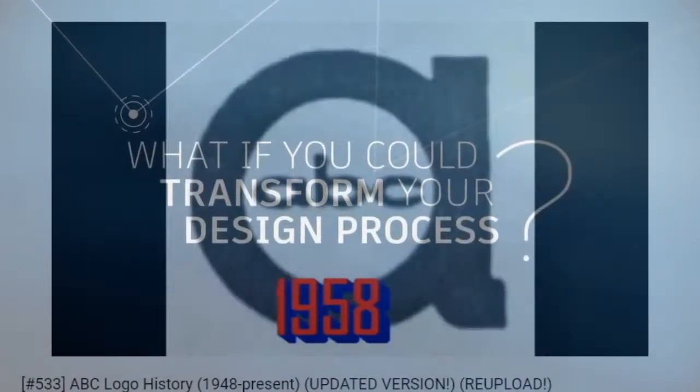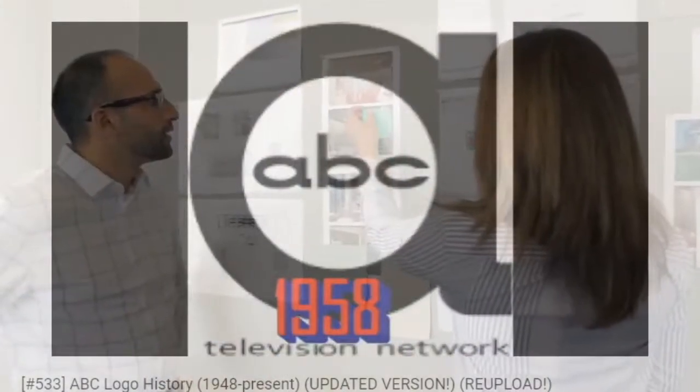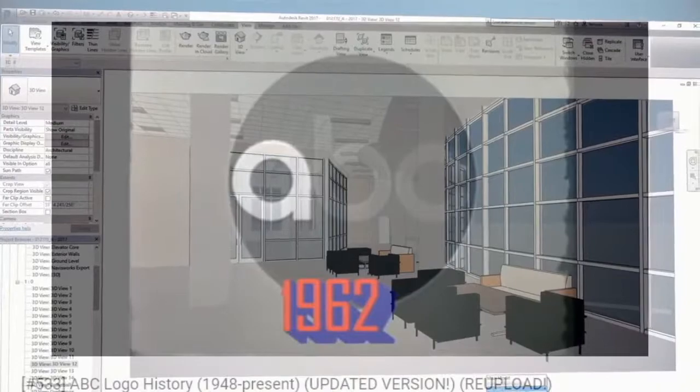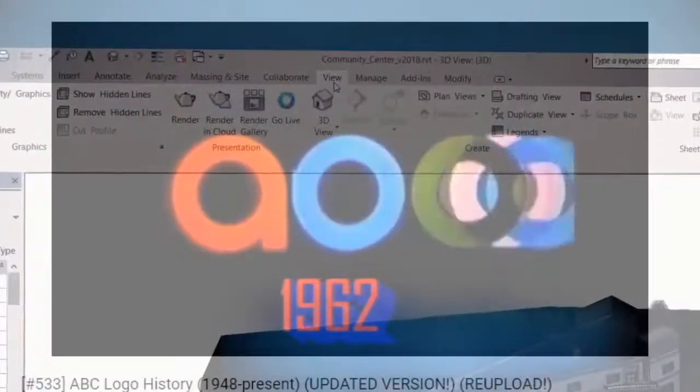This is just thick, I'm modeling thick finishes, and where it's more than just a skim coat, if there's going to be a topping slab. And we still haven't gotten into pitching these, obviously for drainage purposes, right? Floors aren't always flat on the X plane, if you're looking at it in elevation, right? In elevation, sometimes there'll be a pitch. There may be a pitch, like in a shower, right? Or any draining floor, whether it's a drain.